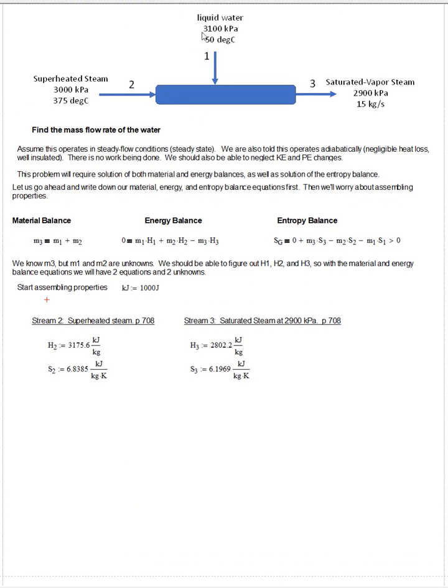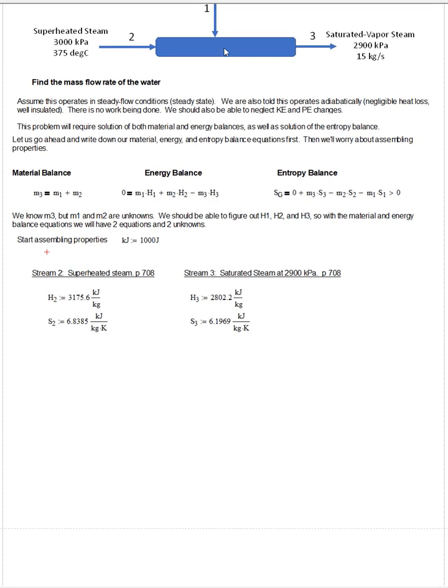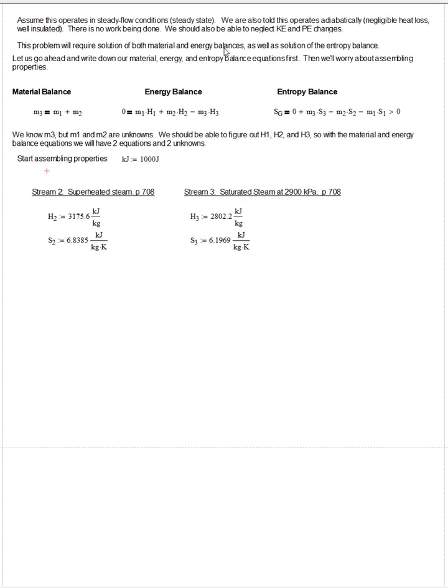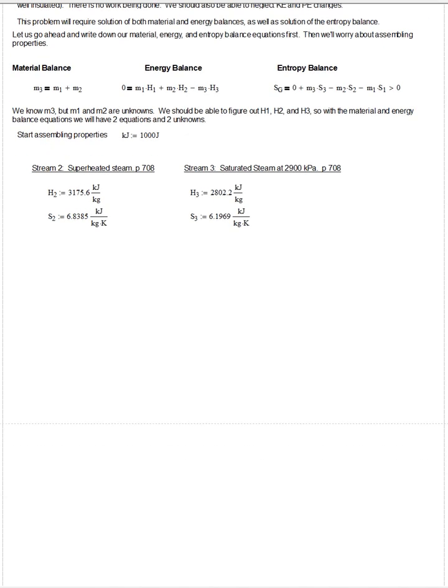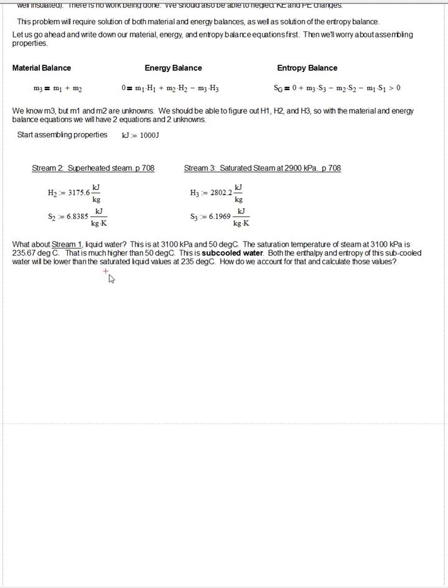What about this liquid water, 3100 kilopascals at 50 degrees C? Is this saturated water? Well, if you don't know the answer right off the top of your head, what you'll have to do is go to the steam tables and figure that out.